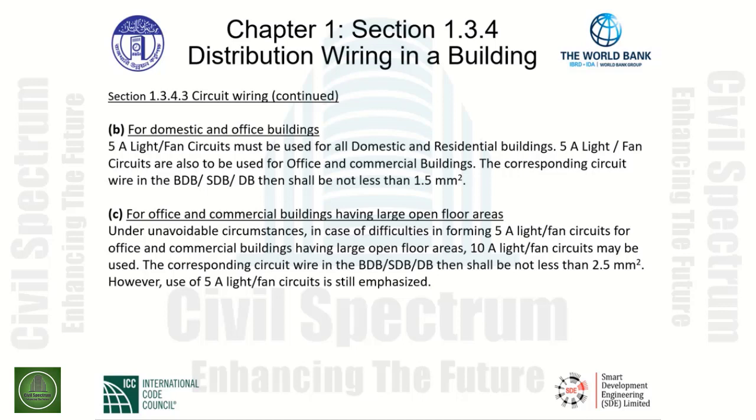Item C, for office and commercial buildings having large open floors. Under unavoidable circumstances, in case of difficulties in forming 5-amp light fan circuits for office and commercial buildings having large open floor areas, 10-amp light fan circuits may be used.